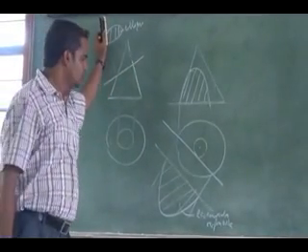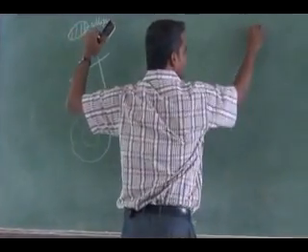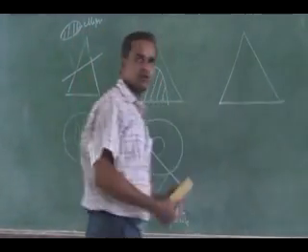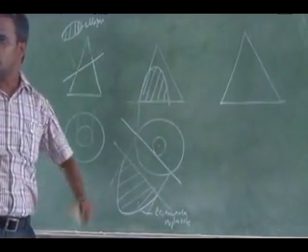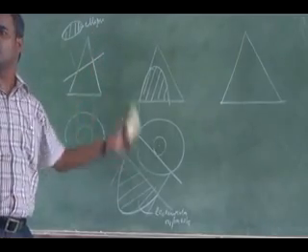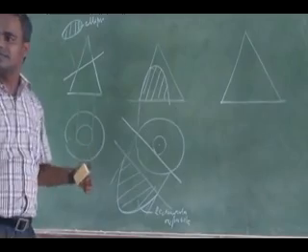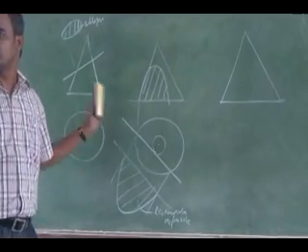Similarly, if the same cone is cut, these problems you should remember. What is the true shape we will obtain? You have to represent the cutting plane and mark the cutting points as usual. You have to get the front view, the sectional top view or sectional views, and the true shape of the section.